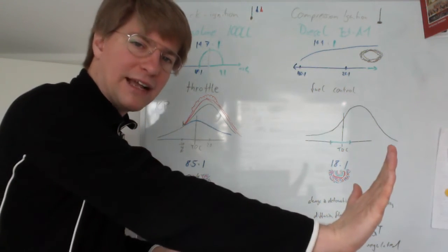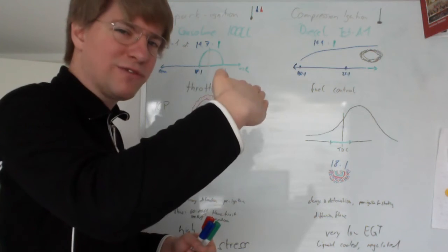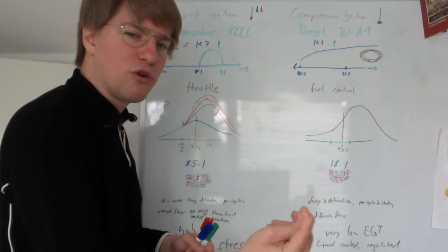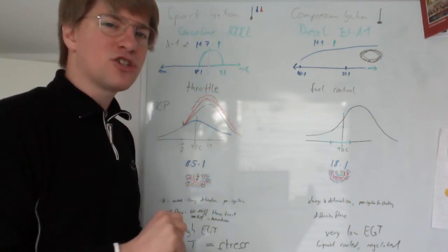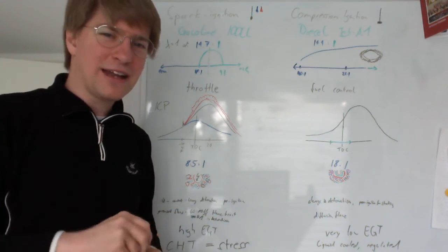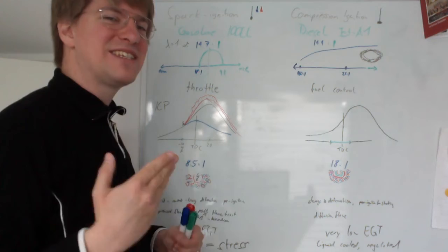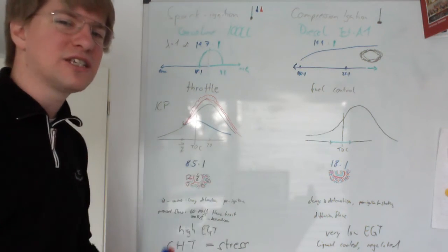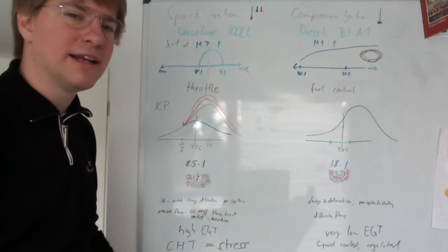The black knob is always in, the throttle is always fully open, there's no way to close the throttle, and the only power control is the mixture lever, and while you're doing that, you are running in constant detonation. This is the way to understand the diesel engine for a pilot.